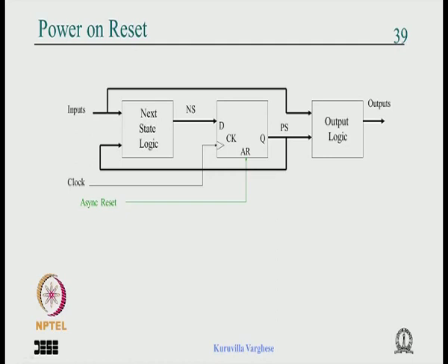It can go to some other state and wait for some input, but at the beginning, at power on, you have to bring it to a starting state, and that is where it is used. And this is simple in VHDL coding because this is combined with the flip flop.